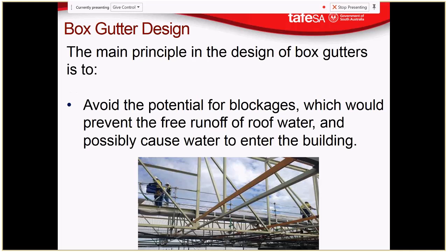So a lot of those have open-ended box gutters, so that the end is open, and then they have a rain head further down with a sloping mesh top. So the water can just flow straight out of the box gutter, be caught by the large rain head with the mesh top, and all the loose bits of hay can just go away. They can sit on top of that mesh top and fly away. And personally, I don't think they're that unattractive. And I think you can use the same sort of scenario on a residential building as well to good effect.